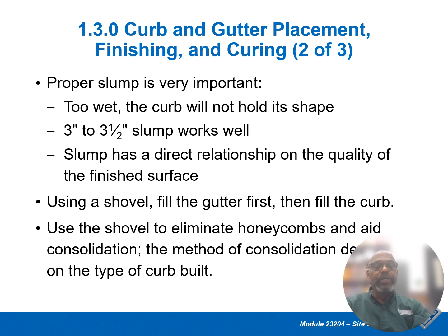Using a shovel, fill the gutter first, then fill the curb. Use the shovel to eliminate honeycombs and aid in consolidation. The method of consolidation depends on the type of curb built.